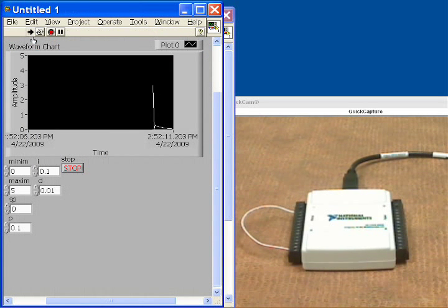So when we go ahead and run this, we'll actually see that white line being the analog output, and then the red line, which you can see there for a little bit, that's going to be my set point. So if we begin to change this, you'll now see the red value, which is the set point that I'm controlling. It's changing, and the system is then responding through the control algorithm to try to match that red value.